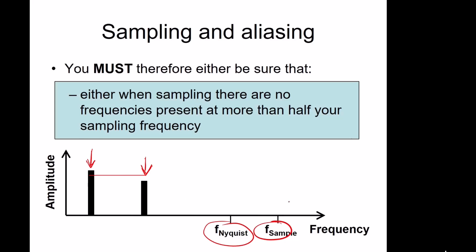The downside, or the two downsides to this, is having to sample at a very fast frequency can be very expensive. The faster the digitizer, the more expensive it is. And secondly, you're paying extra for what is noise essentially up here. You don't care about any of this. This is all that you want, this signal here. So it'd be better if you can just measure this and eliminate anything here.